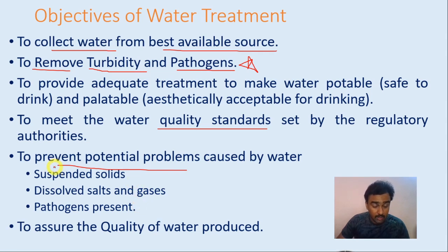The last thing is, I should assure the quality of water. That means when water treatment is considered, I am not only treating the water, I should assure the quality of water. The treated water should not be stored in containers for a long period of time, and disinfection should be given while distributing the water, so that it does not get contaminated while distributing it to the community. Along with the water treatment, we also assure the quality before sending it to the public. Now I will end this session.